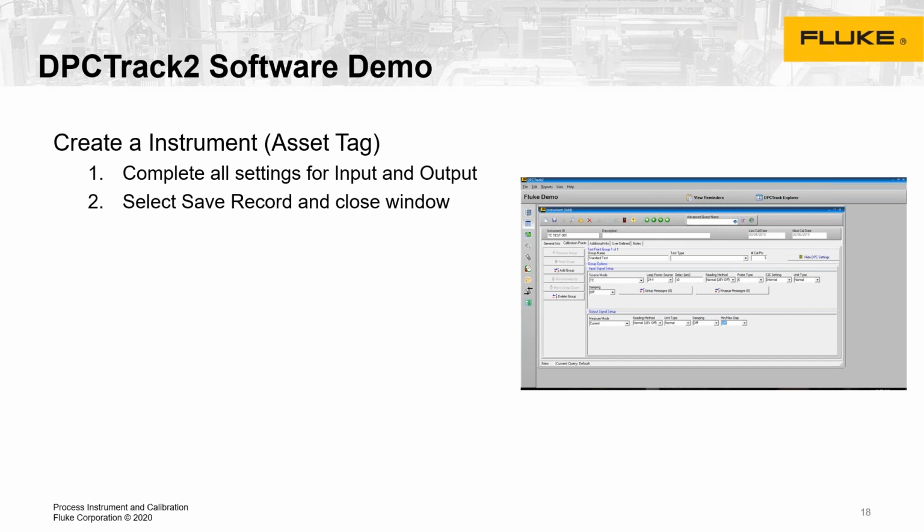So if we want to use the radio to call the control room and say, I'm giving you 100 degrees Celsius, what are you feeding back? You can't measure what the control panel sees 100 yards away, but you can manually enter it if you're using a user entered value selection.